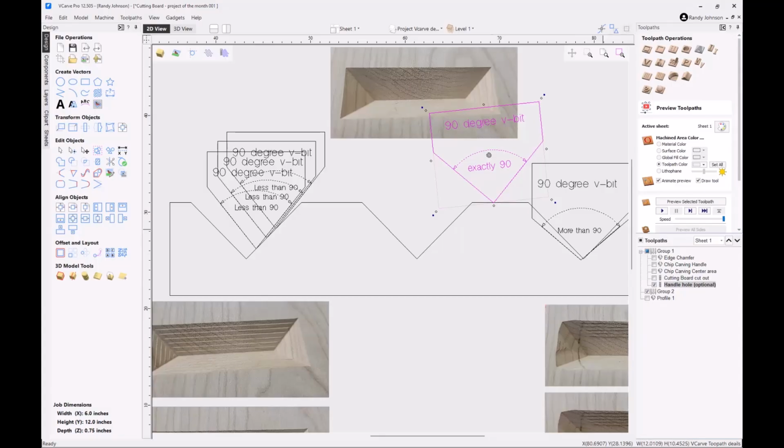Oh, Randy? Yeah. Okay, it's the other way around. You said if it leaves a dot, it's out of tram. It's actually the other way around. If it leaves a circle, it's not aligned. You are correct. When I said dot, I meant circle. If it's leaving anything but a little small spot, you are out of alignment.